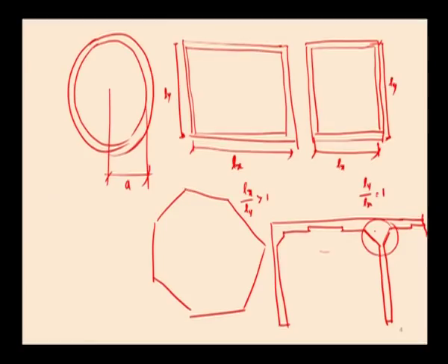In order to resist this maximum negative bending moment as well as the shear, the amount of concrete has been increased, that is, the size of the column has been increased. The increased or enlarged portion of this column is called the capital. This much concrete has to be used to resist this negative bending moment as well as the shear force, and near the middle of the span we have the slab portion.